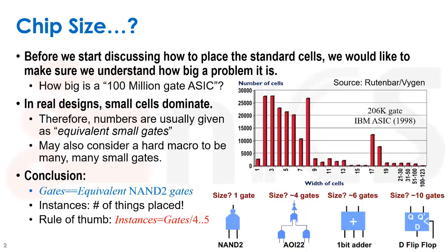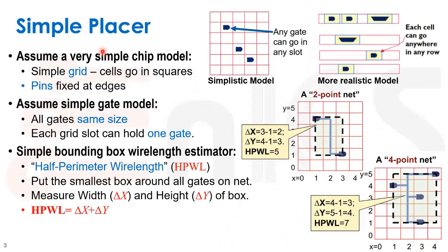If we listen to the lecture, we saw that when we were designing our simple placer, we had to give some sort of cost metric, and cost metrics are really important. We have to have a way to measure how optimal we are, and we have to have some sort of function that we are trying to optimize. What we decided basically in placement, and this is a decision that takes a lot of years of experience and some estimations, is that we think wire length is a good estimator to optimize.